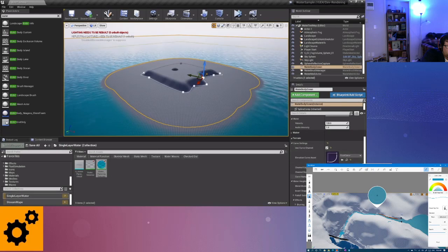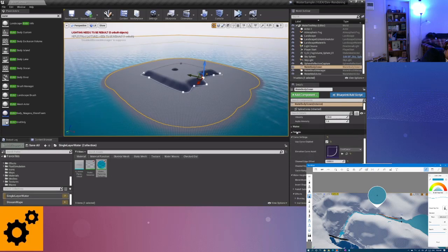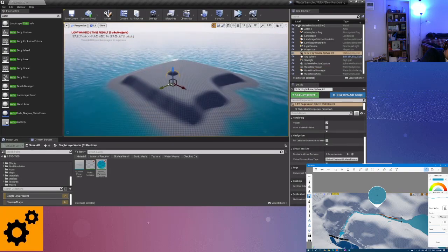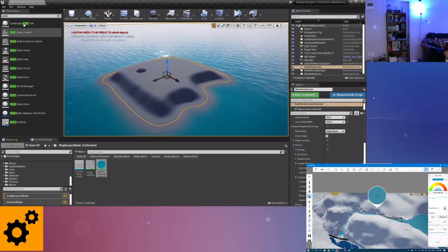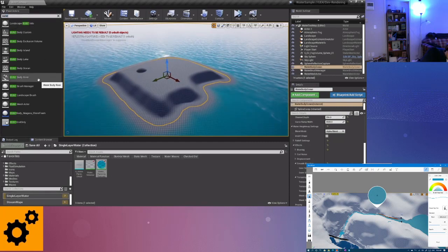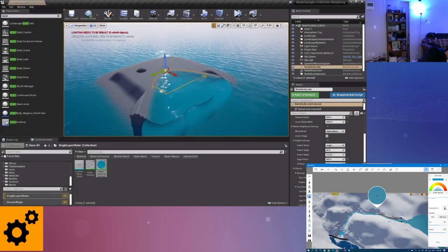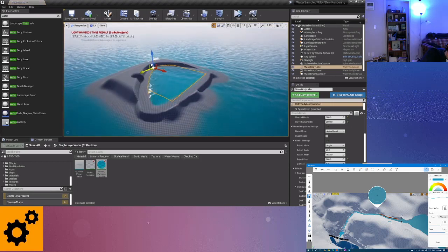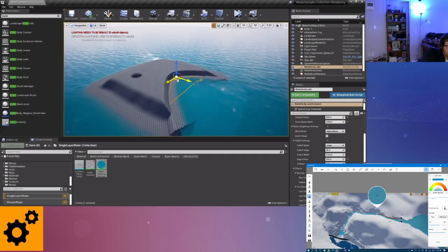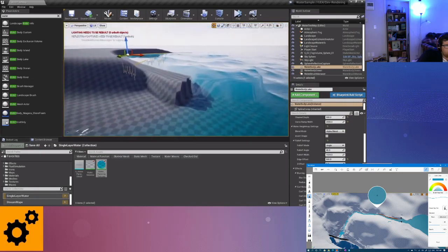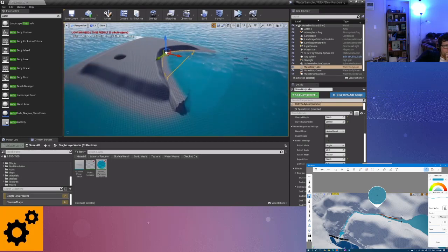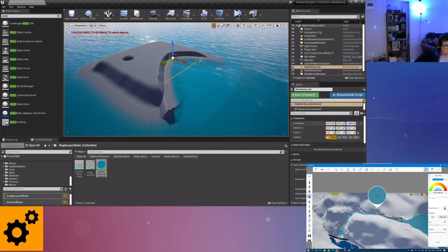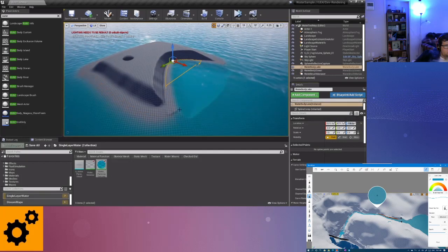Let me go ahead and remove some of that crazy edge offsetting. And then I'm going to go ahead and recreate a little bit of that scene we had here before. So now we have an ocean. I'm going to go ahead and drop in, how about a lake? So one thing that is kind of a limitation with the system right now is it will not blend, say, a lake with an ocean. So if you try to put a lake overlapping an ocean, what you're going to get is something a little weird. But what you can do is place them at the same Z height. And then you could use the material to fade in some custom stuff there.